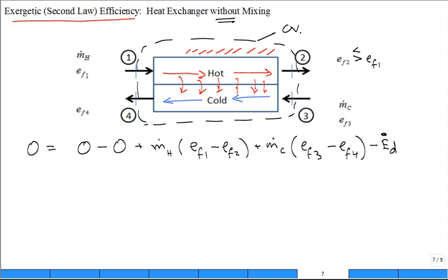I have a less than. It's less than, isn't it? You think about a hot fluid stream. It has a lot of potential to make work, useful work. Let's say I have a lukewarm fluid stream. I have less potential to do work, true? And so EF, the flow exergy, is the measure of how ready it is to make some useful work, okay?